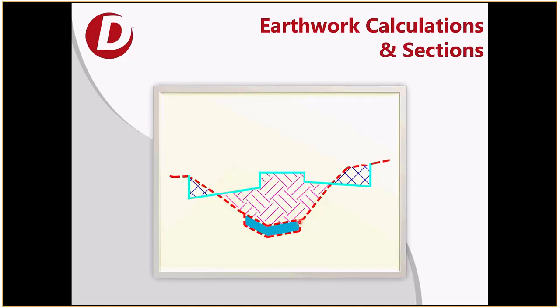I've seen it happen before. You've got 3 or 4 inches of existing asphalt. You're going to put embankment on it. You're really good about surveying it correctly. You're really good about calling out removals during your demolition quantities. But if someone forgets to, we've got to lower our ground line 4 inches to reflect the fact that we've removed that quantity of asphalt from the ground, and that's got to become our new existing ground line. So keep an eye on any removals like that.